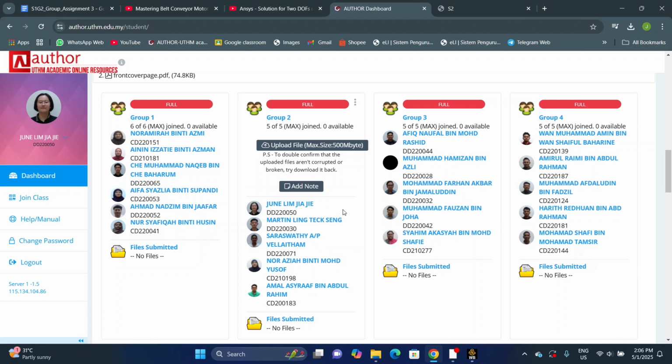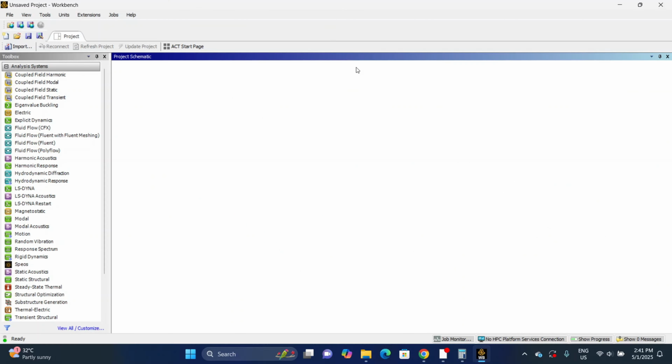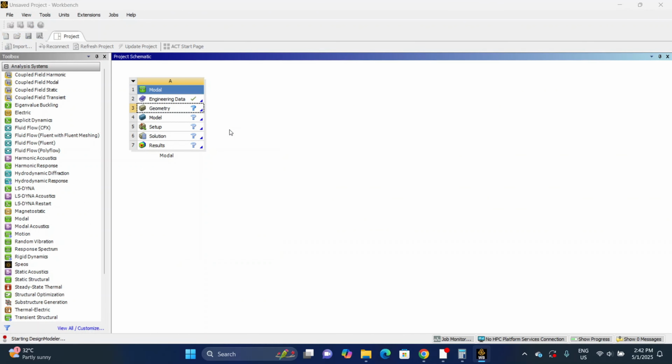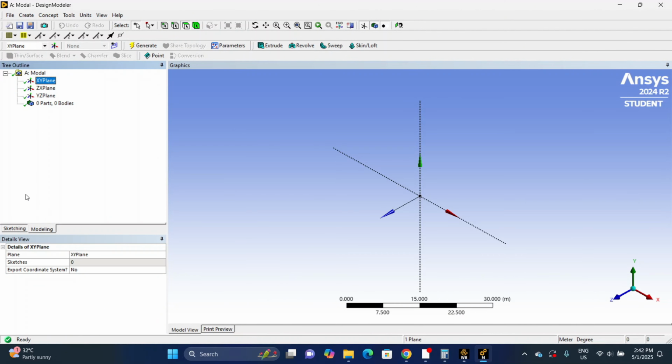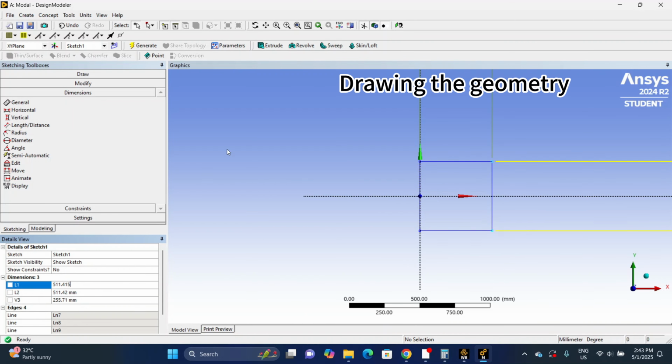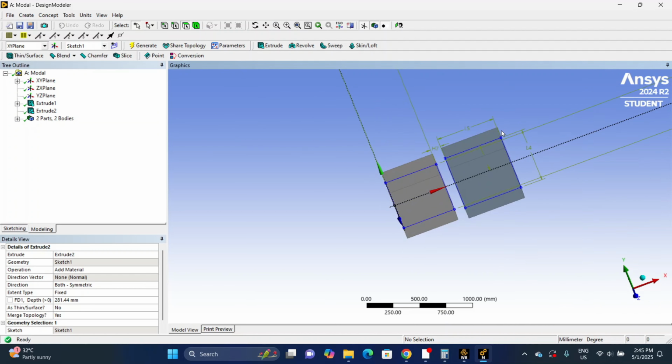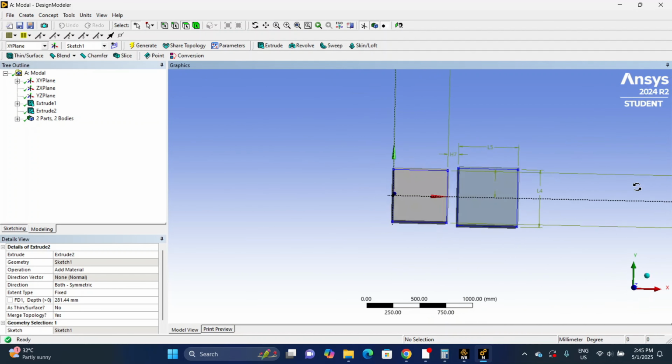In this video, I will be presenting the validation method for our assignment 3 using ANSYS. First of all, the first step is to open the workbench of the ANSYS. Then we create a model. Then we create a geometry using the dimension we just calculated. First of all, go to the XY plane. And then we have just done drawing our mass, our passenger coach.